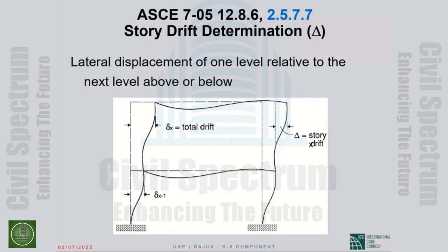Now, there are two exceptions to what I just said. Yes, our codes are life safety codes, but in two situations, we seem to go beyond life safety. One is where we impose a limit on inter-story drift. That is more than life safety. We are now trying to prevent or minimize damage to non-structural elements.